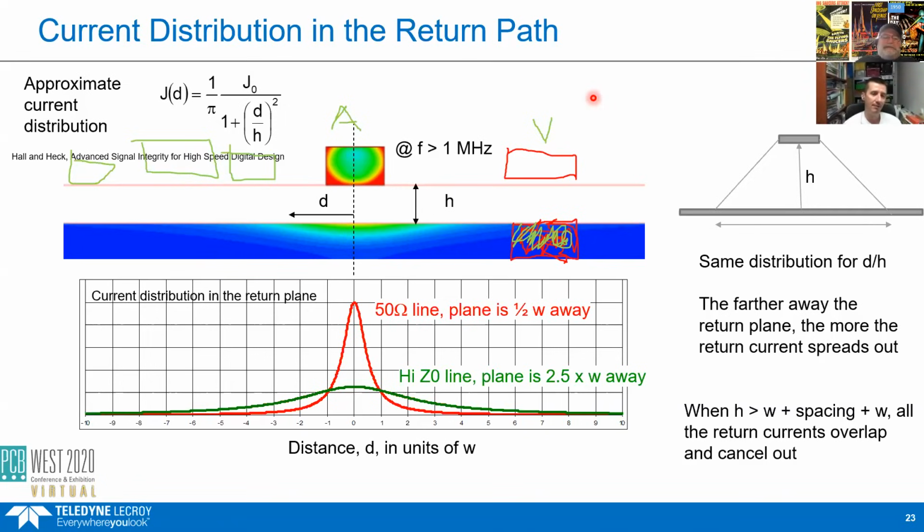So there are a lot of folks that say that. Ground bounce is a form of switching noise, and not all crosstalk happens at the edge. It's the edge that drives it, but the signature of the noise that you see may last during the period of the signal as it's propagating. And so many people say, if I have switching noise, and I can keep that outside of the setup and hold time for the receiver, then who cares. And generally, that's mostly true.